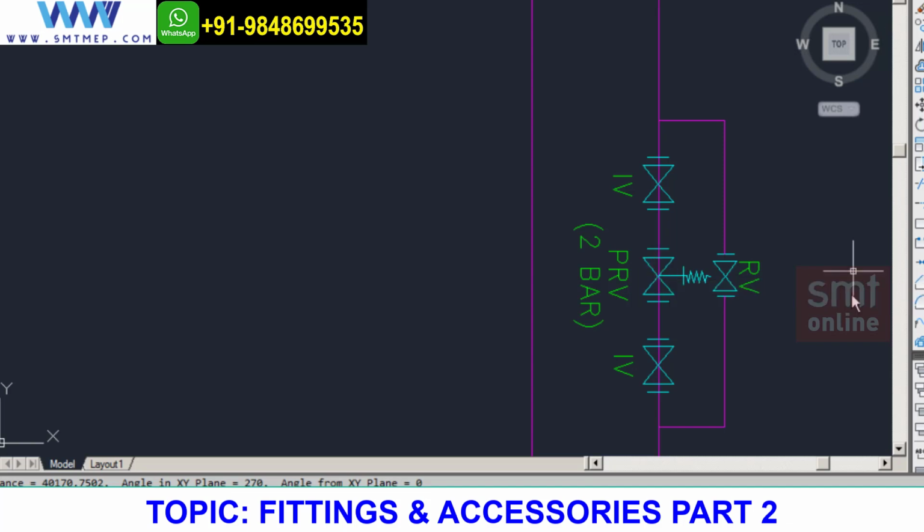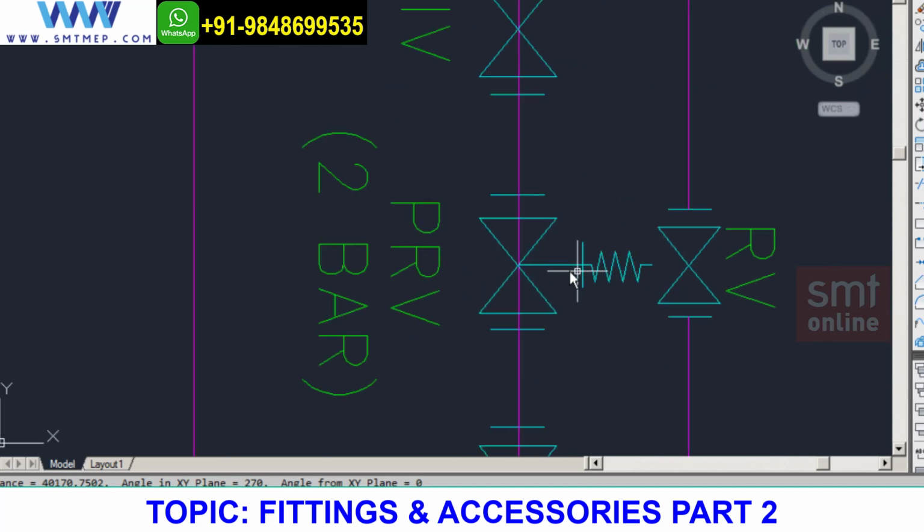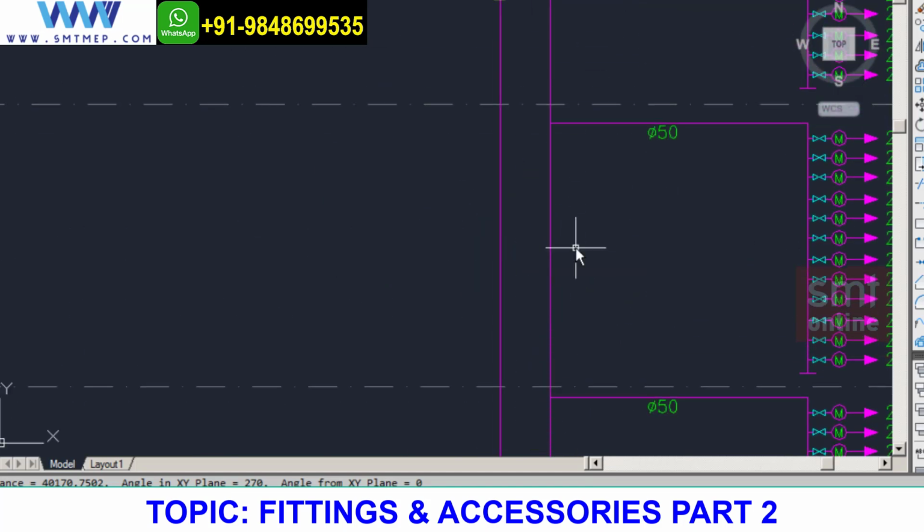Now, I have a formula in firefighting. You'll be selecting the pressure exerted at the bottom. That means the pressure over here, because as the gravity is increasing, the water pressure will be increasing more and more, isn't it? So I need to calculate the pressure where I'm getting a pressure of 60 psi or 80 psi. I need to know that.